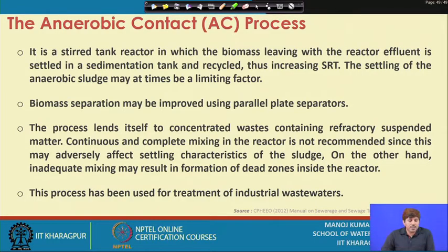If we see, the anaerobic contact process is essentially a kind of stirred tank reactor where mixing is ensured for contact of the biomass with the substrate. The biomass which is leaving in the reactor effluent is settled in a sedimentation tank and recycled back. That way the sludge retention time is increased.